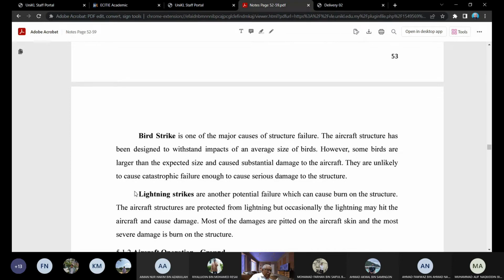I experienced this myself, during landing of one of the US Air Force aircraft, when I was working for Aero. The bird hit the flaps at the down position. It flew under the wing, hit the flaps, and then the bird punctured the skin of the flaps, went inside, and smacked into between the flap ribs. Then we were asked to repair. So I went there to inspect the aircraft, and we had to remove all the bird mess first before we could inspect the extent of the damage.